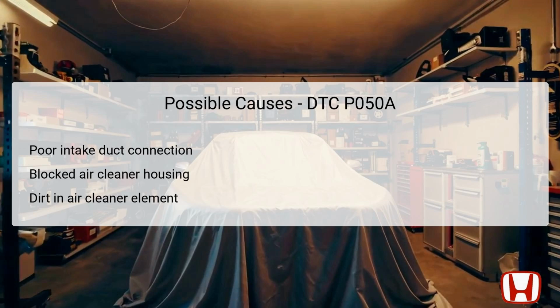If the air cleaner housing is compromised, it can impede the necessary clean air from entering the engine. Additionally, the air cleaner element itself can become dirty or clogged with debris, which directly restricts airflow and can lead to performance issues. Therefore, each of these potential causes should be carefully inspected.